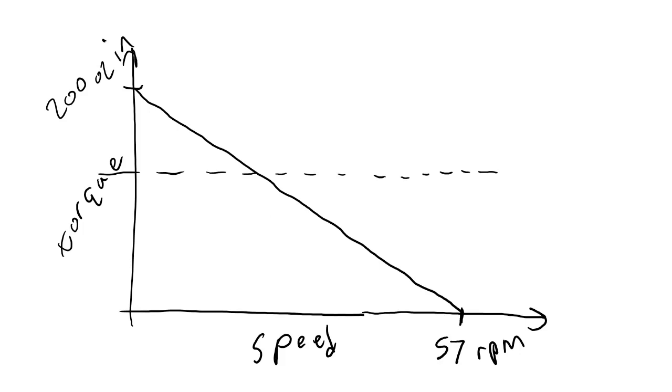Back in our torque speed curve, we now know that we need the point 140 ounce-inches and 30 RPM to be underneath this curve. But in this case, this point is so close to the line, I can't tell by eye whether the point is above or below. Let's do some calculations to figure it out. We could write this torque speed curve using y equals mx plus b.